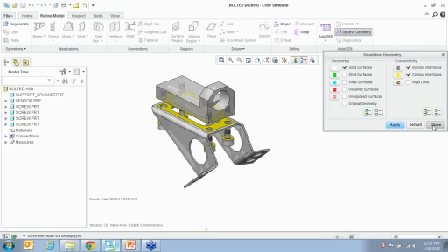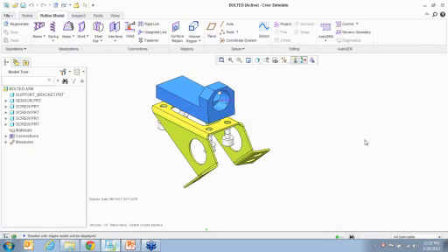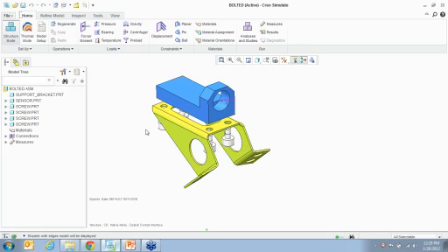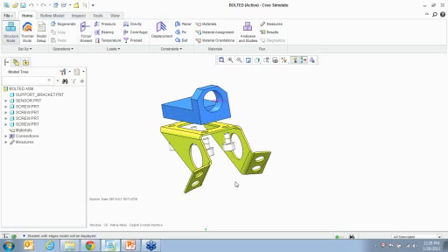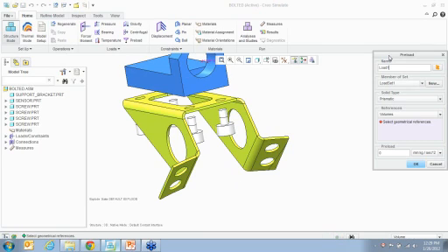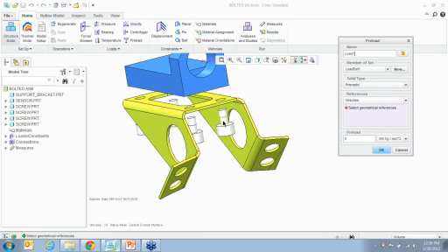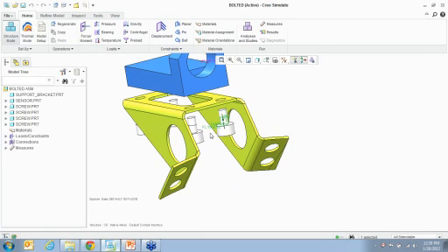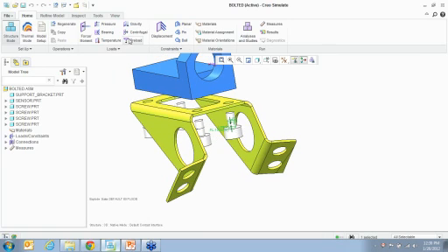All right. Now let's go ahead and run an analysis on this model. What I'm trying to simulate here is I'm going to put these bolts in here and tighten them up such that there's 1,000 newtons of preload. Now, how would I apply a preload? Here's the icon for it. Load 1, load set 1, prismatic, volumes. Just pick that volume region and say there is 1,000 newtons of load on it. It automatically detects the prismatic volume region's axis and determines which direction the load is acting.